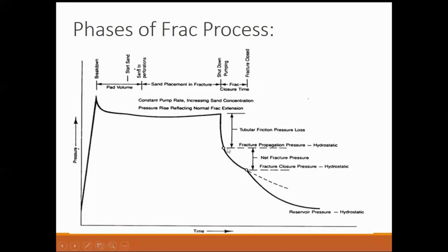Then at this point, the pumps are stopped now. Now the frac, and this is it. It also gives your fracture propagation pressure. So this is the minimum pressure that was actually driving your fracture, or this is the pressure which was propagating your fracture.